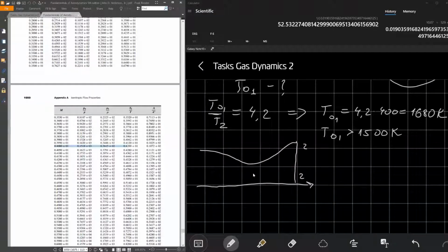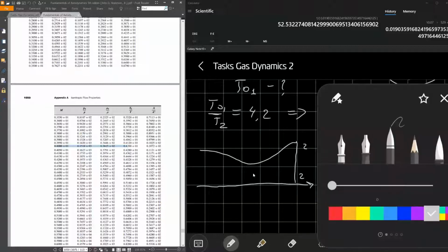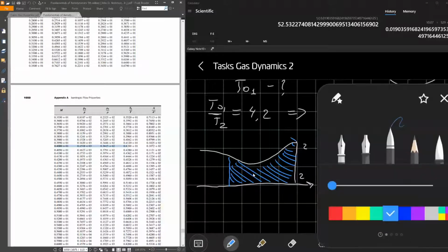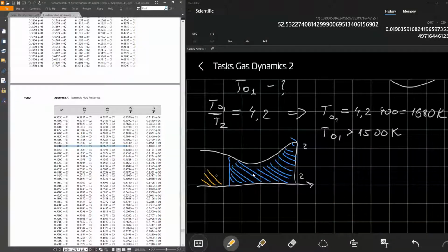And here temperature is small, just using another color. Here temperature is small in this region. We don't know where subsonic or supersonic will be, but I suppose this. And at some region, it's a hot flow, more than 1500 Kelvin, somewhere in this region. So we can find this point. We will call it point 1, transition. In this region, gamma is not constant, here in orange, and inside the blue, gamma, R, Cp and Cv are constant.